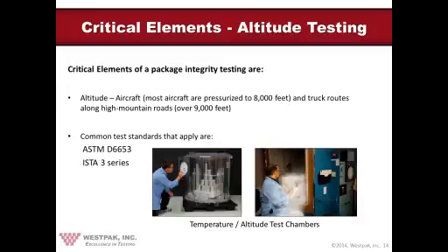Finally, let's not forget about altitude. Packages that are non-breathable can often be altitude sensitive. As you go higher in altitude, the air inside a closed system expands, pushing against the package walls. This is why a closed bag of chips or a bottle of water expands when we travel up in altitude, up a mountain. It's conceivable that a bag or bottle can burst or lose internal pressure as a result of this. I've seen corrugated boxes burst open due to multiple bags expanding within.